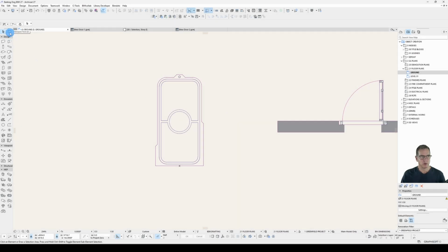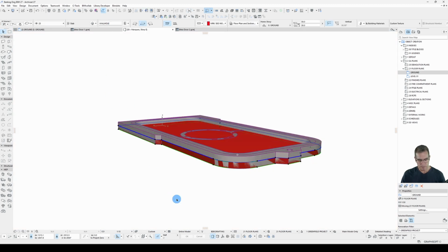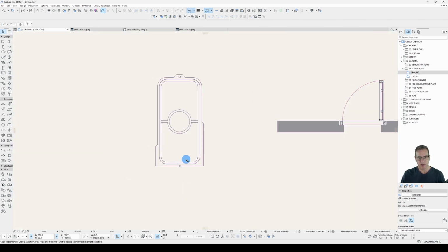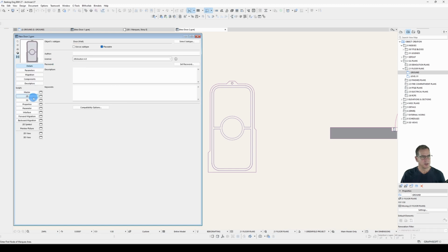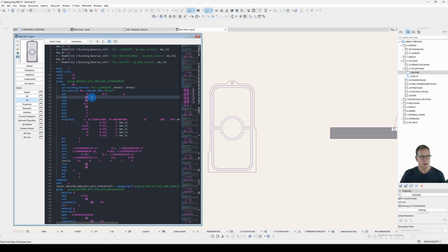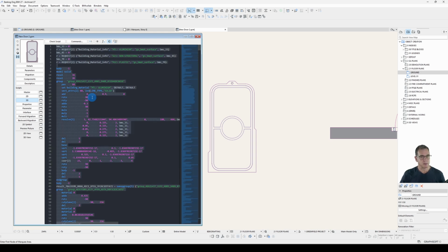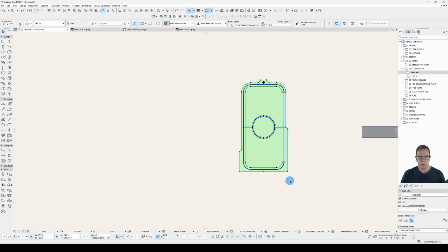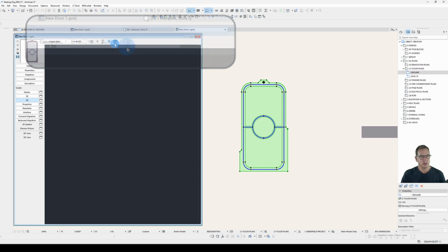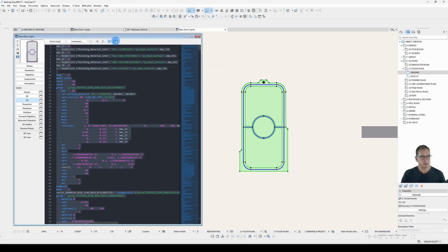With the create from floor plan method, there's my wall hole slab. It needs to be oriented with your door, of course, around the origin with the element ID of wall hole. I navigate to my object, the 3D script, and this differs to the save as method in that I'm not overriding the object, I'm just replacing my 3D script. So I select the entire 3D script using Control A or Command A, delete, select my floor plan geometry, which includes my wall hole slab, and click on my generate button.